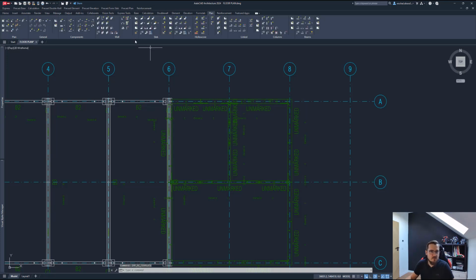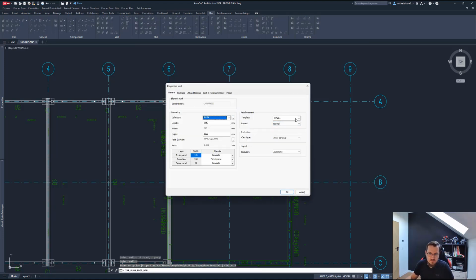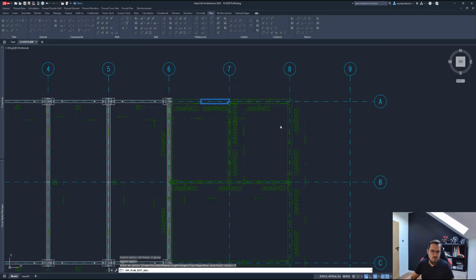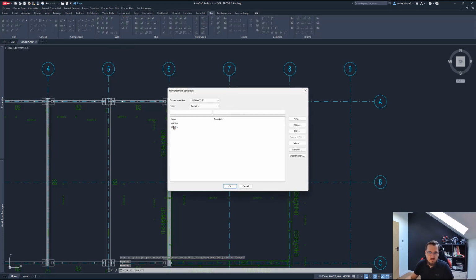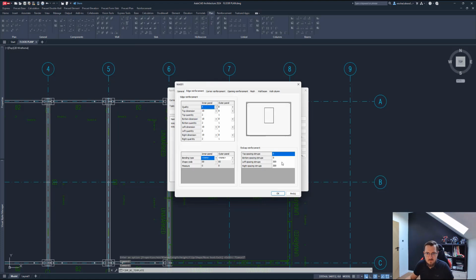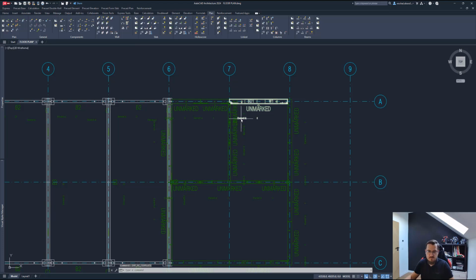To explain what happened here right now, let's go and edit the wall properties. So the walls have assigned a different reinforcement template. So I can go back and edit this one. Basically, the reinforcement template decides on whatever reinforcement is in the element. So let me go ahead and go back to this one, edge reinforcement. Okay, we already have some definition here for left and right side of the elements. Let's make that tighter. 200, right? And let's save that. And that's okay. That's done, really.